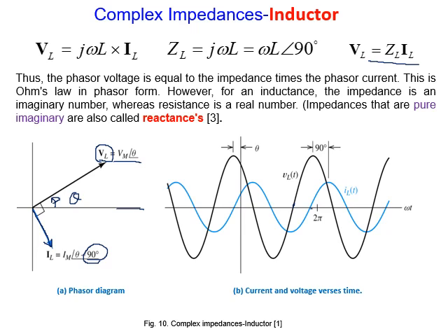This is called reactance. And now you have new terminology. You have resistance, you know it. Reactance, which is usually represented by X, is like resistance but in AC, coming from inductance or capacitance. For inductance we call it XL, later on XC for capacitance. Now this is reactance. The general term for reactance and resistance, by the way, all of them in ohms, is impedance. So impedance is the general name. It could be resistance alone, it could be inductance alone, it could be a mix of inductance and resistance.